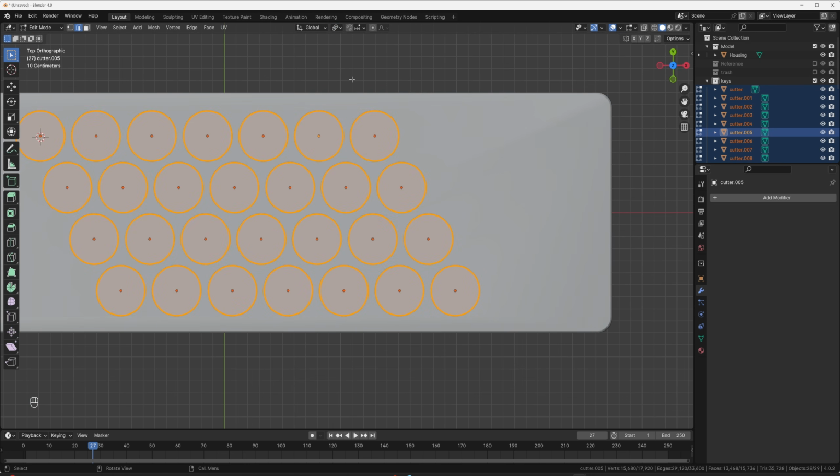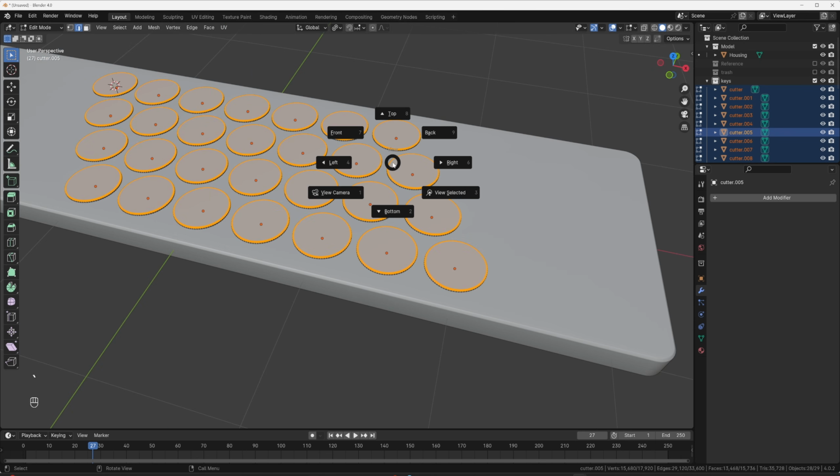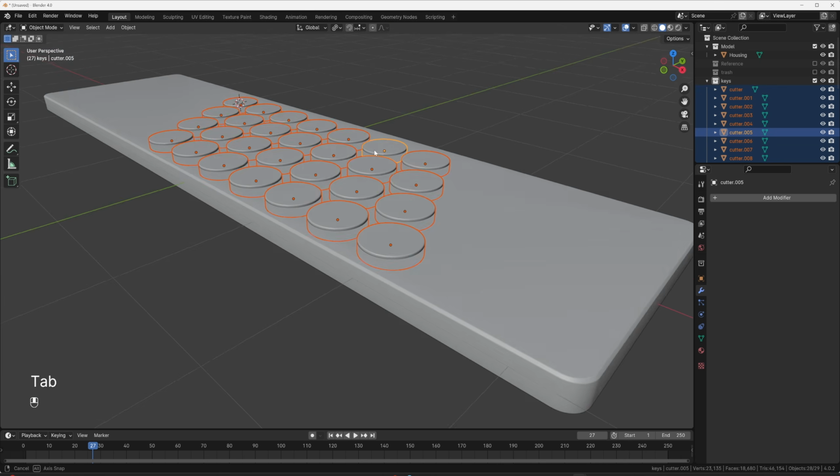to individual origins. If you have a mouse with a couple of programmable buttons, I have mine set to where I can just press the button and it automatically pulls this up. And then I also have one that changes the pivot point. So if I press the button, I can then change what I'm wanting to look at, which are very handy.